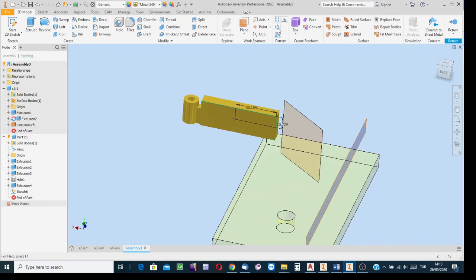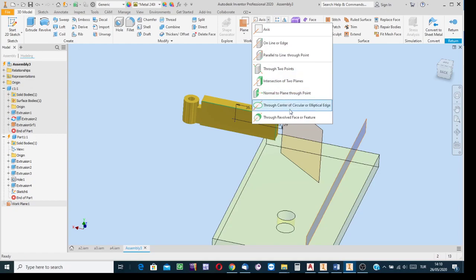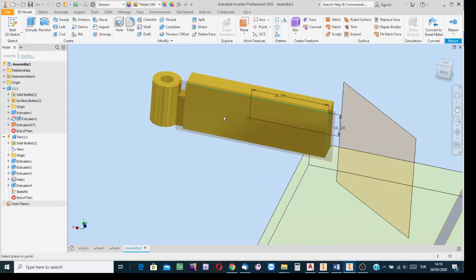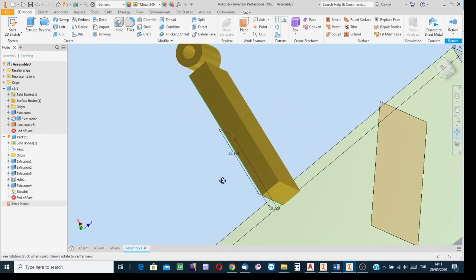Okay, and then click on the axis definition tool. Which one? Normal to a surface, and it is passing through a point. This option. Indicate the surface, say normal to this surface. Indicate this piercing point, and then we have a work axis.